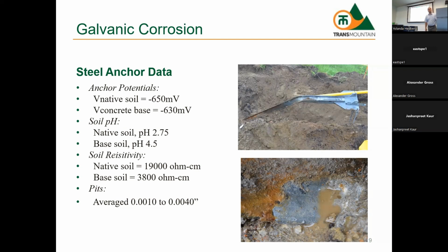So the connection between the copper and the steel, was that something accidental? No, you do that on purpose. The copper, which is intended to ground the structure, has to be connected to the structure. I thought they connected to the top of the, for example, the top. It doesn't matter where that connection is, but it has to be electrically connected. Yeah, it could be at the very top, middle, or right there in the hole. So the error was that if you do have a grounding wire, you have to think about cathodic protection. Correct.